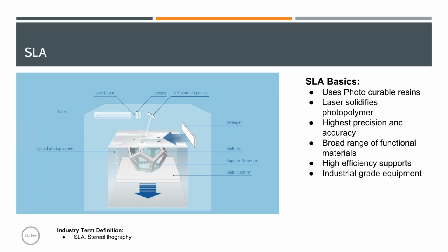For the price point, the Formlabs is a great little printer, but we cannot use that for engineering validation or verification, nor do we use it for that. With production SLA printers, you have a neutrally buoyant part inside of the build vat, so the support material is significantly less damaging to the part. We would consider this wipe away support as opposed to breakaway support.